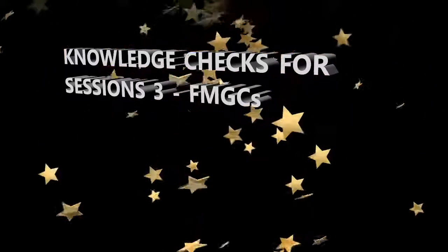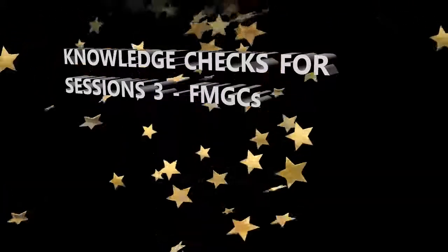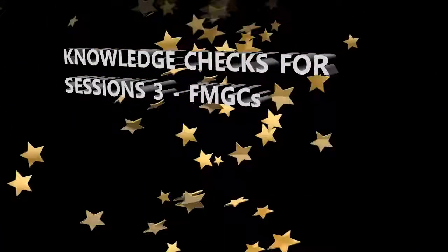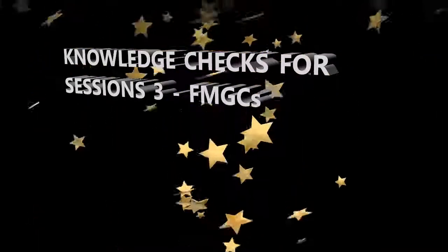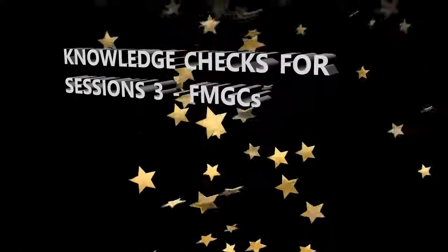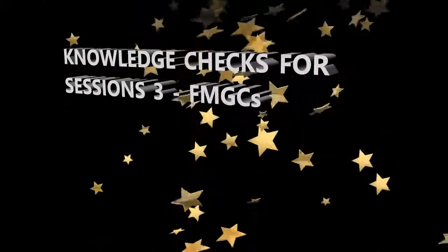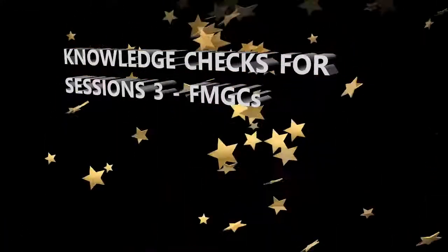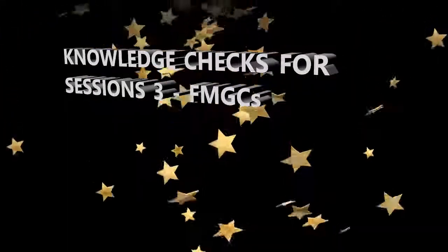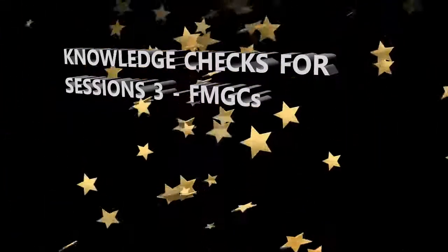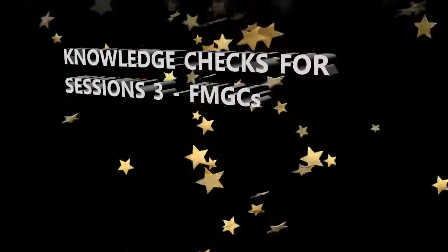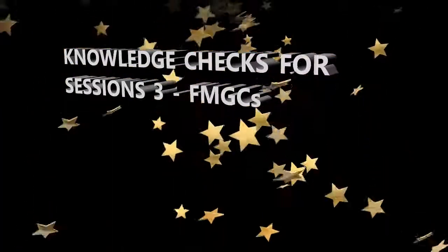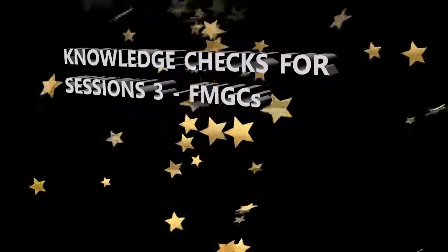All right, that concludes session 3. Let's go ahead and go through just a few more knowledge checks and then we'll call it. The two parts of the FMGC are the flight management and flight guidance. Is that true or false? It's true. All right, the FMGCs are controlled from what two components? Option A is the MCDUs and the FCU, or option B, the MCDUs and the FAC. The answer is the first one, MCDUs and the FCU.